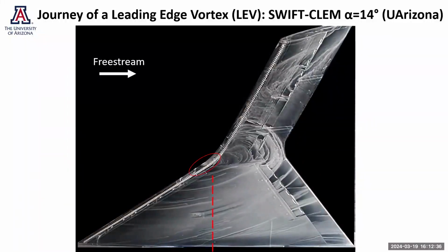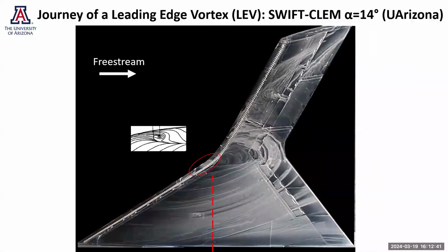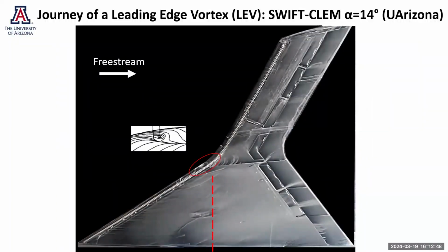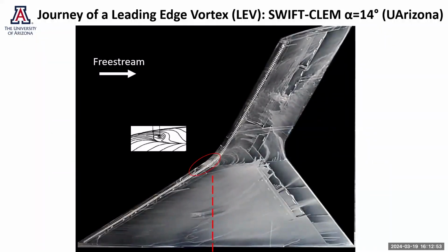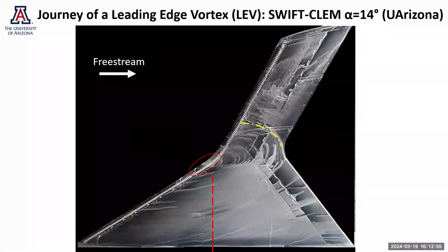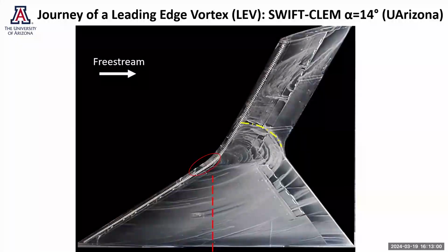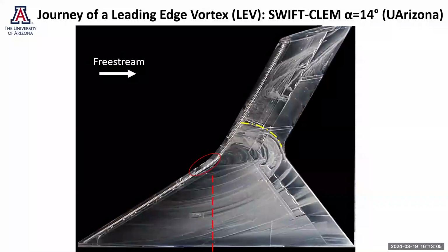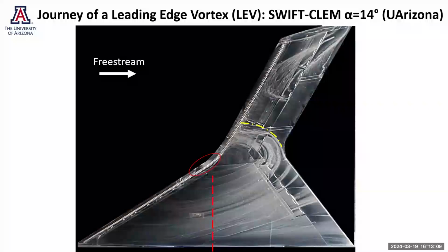Over here, if we focus on this region, which we call the focus of separation, that has been extensively studied in the literature, it identifies a location where the vortex lifts off from the surface. And you can see that surrounding this location or this structure, there are these curved surface streamlines that identify the fluid that is over here being entrained by this vortex liftoff process. And you can see a pretty nice boundary over here.